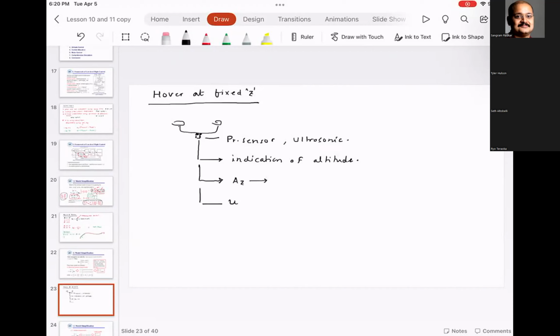But you have the ultrasonic sensor, and that will give you the distance. But whether your Mambo is here or whether your Mambo encounters a step, the distance given by the ultrasonic sensor is going to be unreliable.